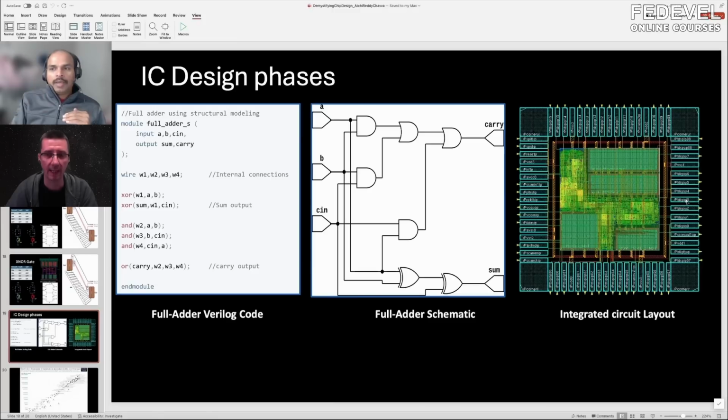And remember, a question from our Discord: someone asked why there is this 1 volt power supply on the chip. This is exactly the reason, because some parts of the chip may be running on much lower voltages, and we need to power it up somehow.